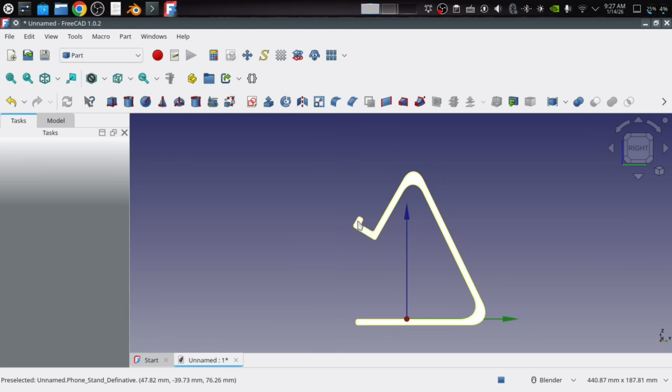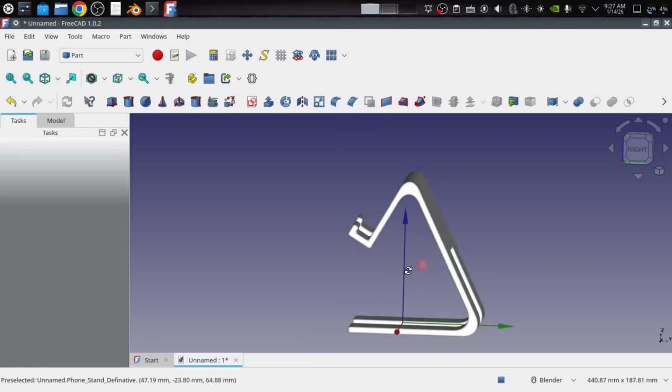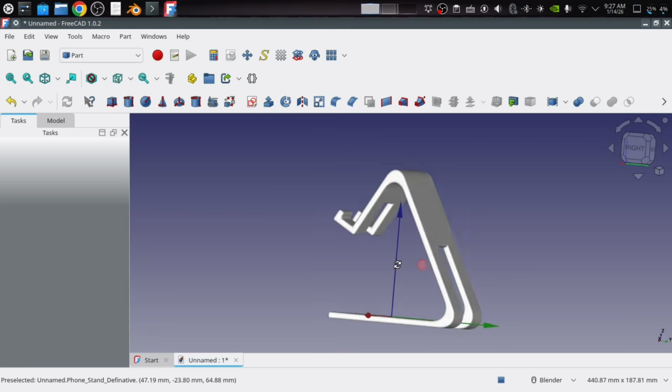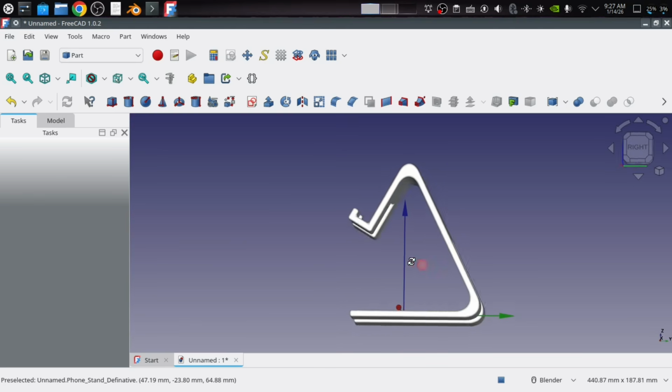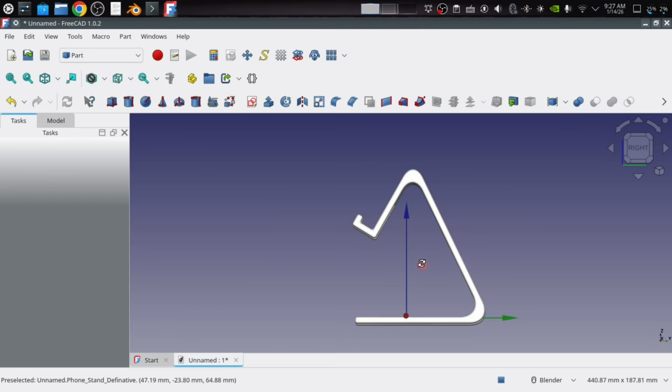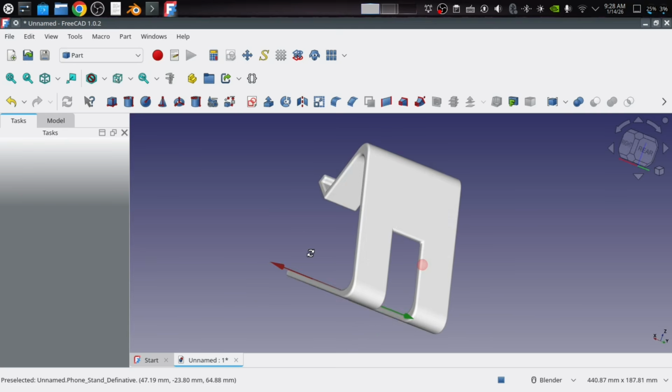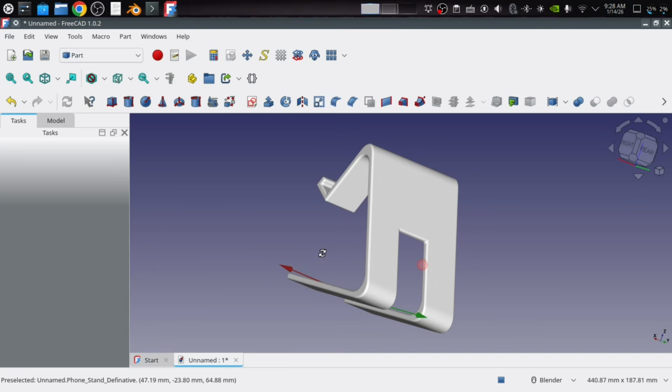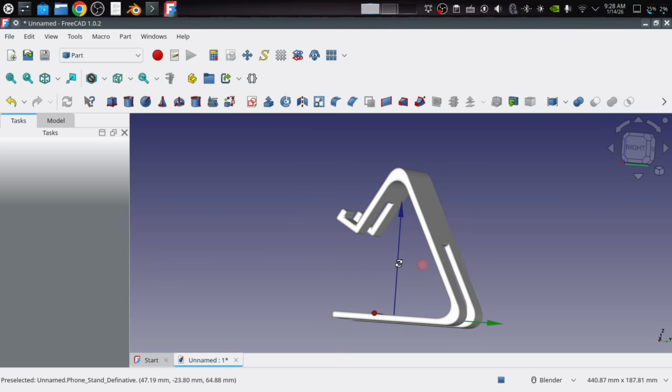That might also affect distances on certain things in certain other parts of the model, though, and it would distort certain parts of the model, so it's not really a perfect fix. But anyway, how would you do this in FreeCAD? Well, we could go through the whole process of conversion of this STL into a FreeCAD object, but we're going to have tons of faces. It's going to be slow to work with. And how would you reduce the size of this? You'd be better off just recreating it from scratch, really. It would just be way too much work. You could cut.